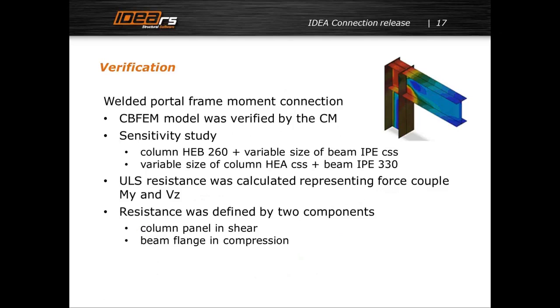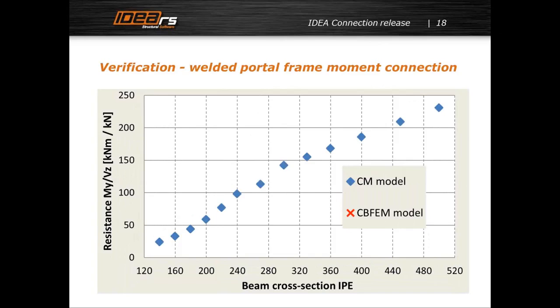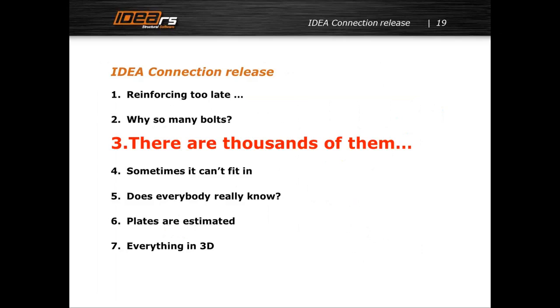We do verification studies like this knee connection. You can see the results calculated by the component model and the results calculated by SBFM, and the agreement is less than 5%. The same we have for bolted connections and base plates.